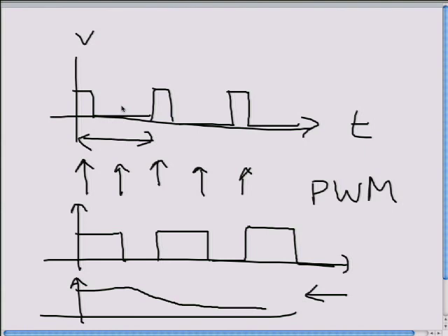A single power transistor connected to a power supply can deliver an enormous amount of power, but it's either on or it's off. When it's on, it's delivering a lot of power. When it's off, it's not delivering any. And that's a much simpler circuit than an amplifier that has to maintain linearity and deliver a lot of power. So linear power amplifiers are very expensive devices compared to the circuit that you need to deliver power through an on-off scheme.